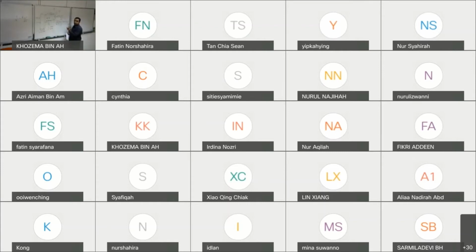So it's better if you go one by one. If you have a watt here, this is the unit we want. Then we have a meter, so we have to find a way to cancel out this meter. I know I have 2 meter here, meter squared, so I cancel out my first meter. Then I go back and I see here you have degrees Celsius. If I look at this whole equation, the only other temperature unit here is Kelvin. So degrees Celsius must somehow cancel out with Kelvin.